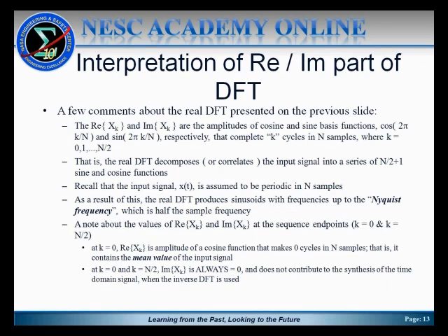So if you're sampling some input sequence as a function of time, then half of the rate at which you sample it is referred to as the Nyquist frequency. The consequences of that we'll discuss again with an example at the end of this presentation, referring to the Shannon Sampling Theorem.